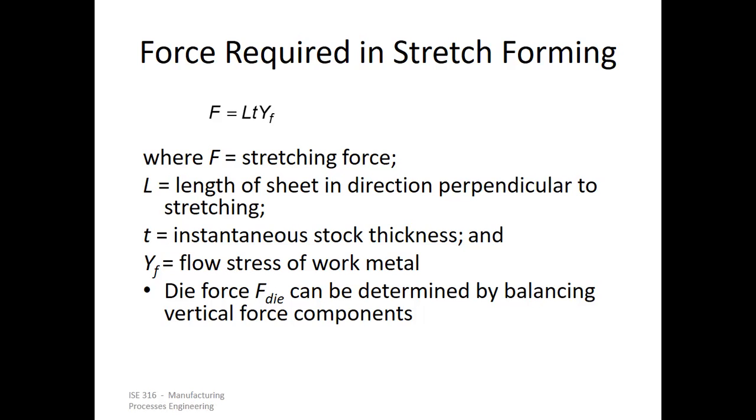And YF is the flow stress of the work metal, and the die force DF can be determined by balancing vertical force components, right? As we know, as per that action-reaction example, we can have that die force. Now you see, what we are looking at is the force equation that is required in stretch forming.